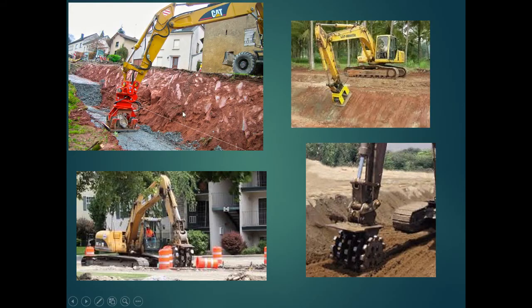All right, so when we're doing trenches, we're always putting in lifts. Here's a plate compactor attached to an excavator, doing a slope. And yes, they do make these for backhoes, so we can actually compact cohesive soils. So make sure they're using the proper equipment: sheep's foot for clays, plate compactor for all others.